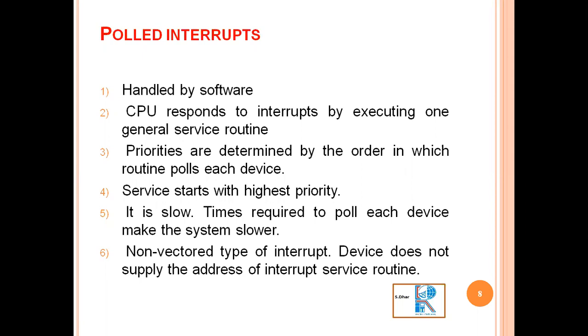Suppose it requires device 10 to be the highest priority, not device 2. Then it will change in the program. Device 10 should be the highest priority, then comes device 1, then device 2. In this way, it can change the priority in the system using software. Clear? So it is flexible, but as it is driven by software, its speed is very slow. This is a slow technique.